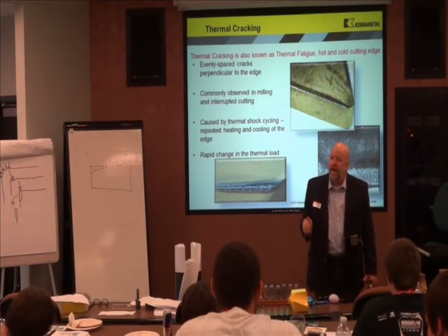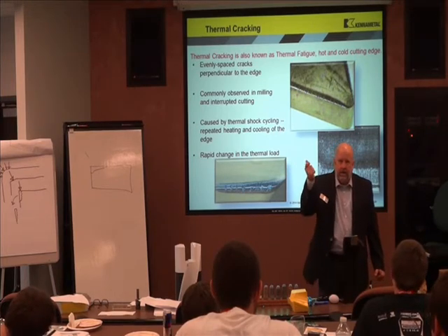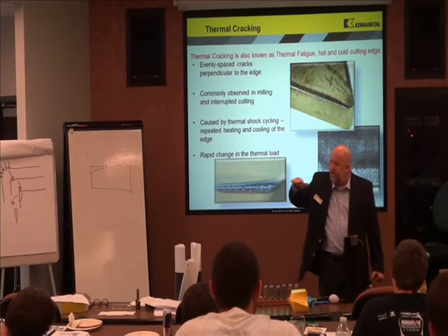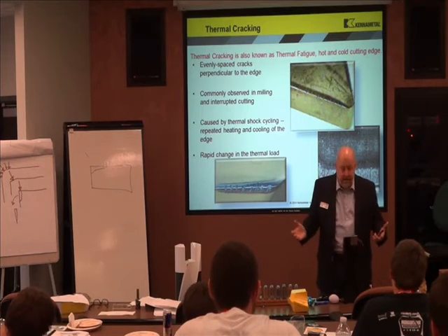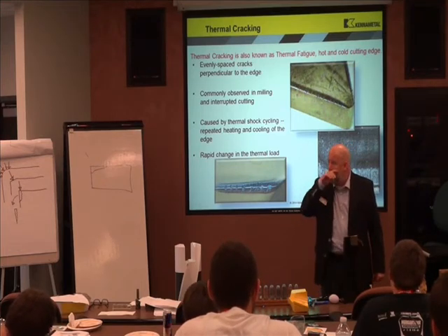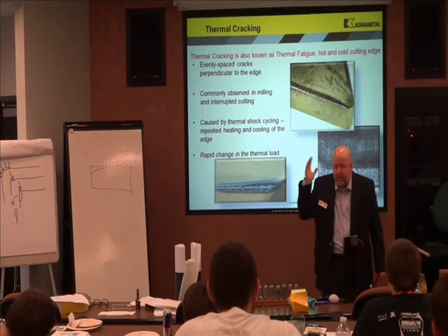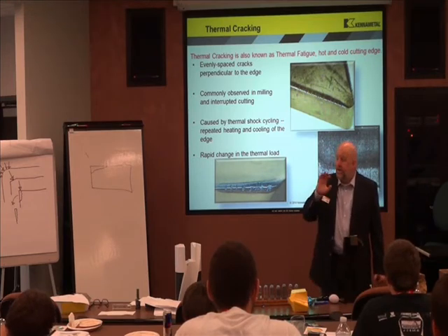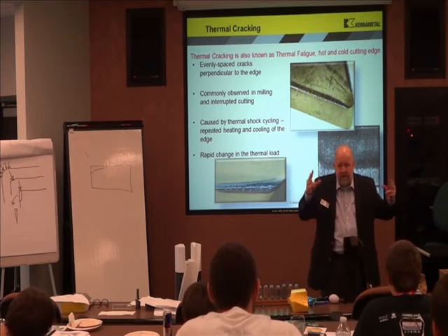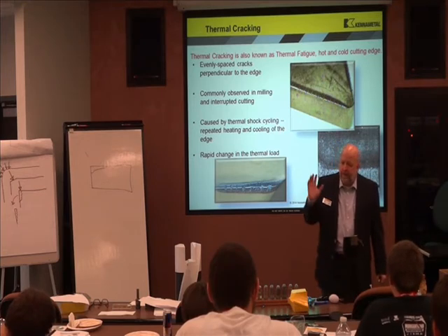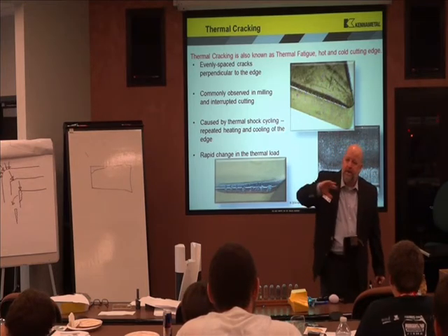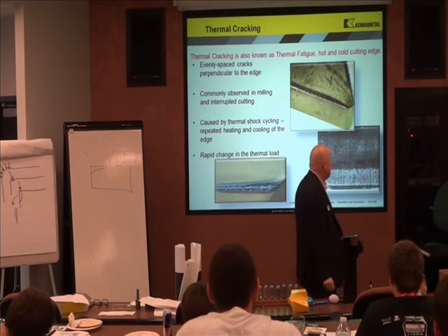Now there are times I have to run coolant. Stainless steel, sometimes to get a good surface finish. High temperature alloys, you have to run coolant because your tool will never last if you don't. Sometimes cast iron to keep the dust down. But a lot of time you can run faster speeds and get better tool life without coolant in milling.